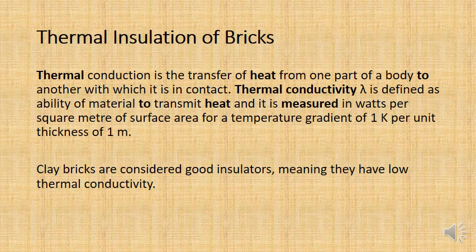So we've talked a little bit about thermal insulation, but I'm just going to talk about this again. Basically, the measure of thermal conductivity is about how easily heat transfers through a material. That is given the symbol lambda, and we measure it in watts per meter Kelvin.